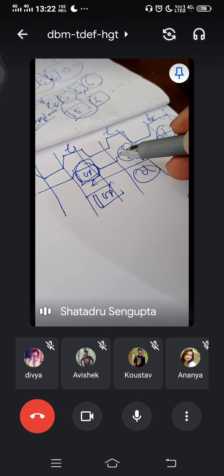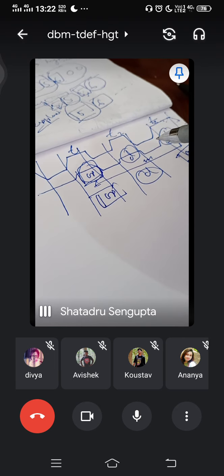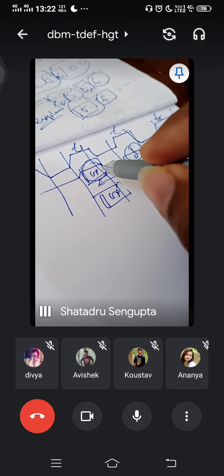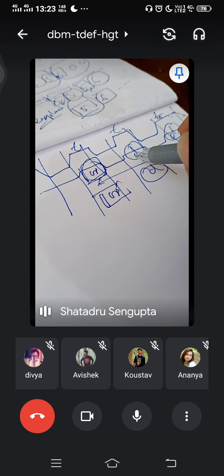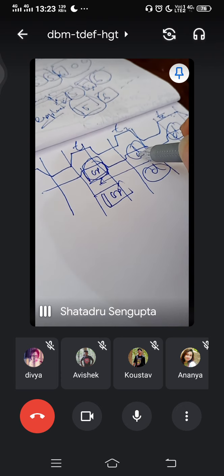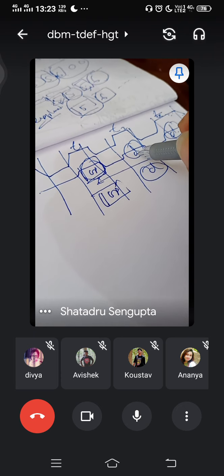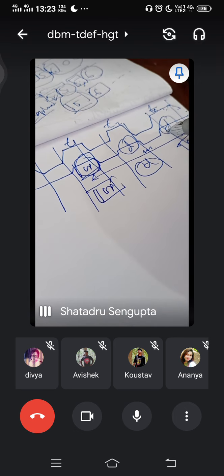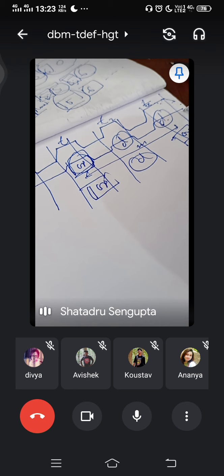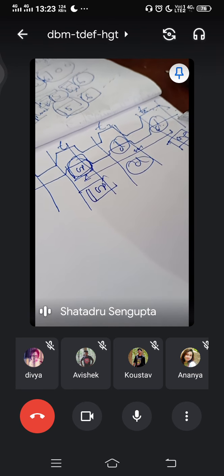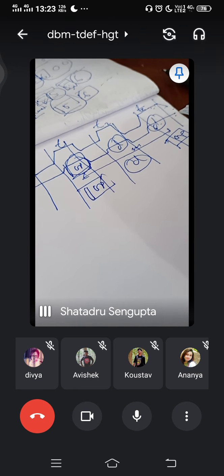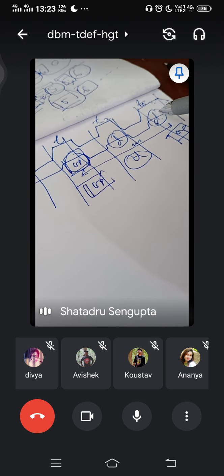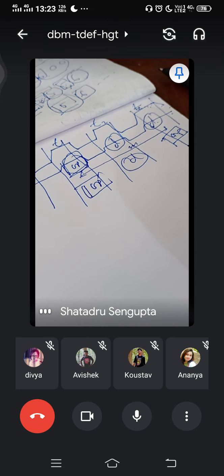So this timing itself tells the computer, not us, the computer rather. First clock pulse, the data comes in, is operation. Second clock pulse, according to this, it will be either another operation or a data. Third clock pulse, according to this, will either be another operation or a data. Fourth clock pulse, according to this, will either be another operation or a data, and so on and so forth. Then in that case, that will be a separate machine cycle altogether.